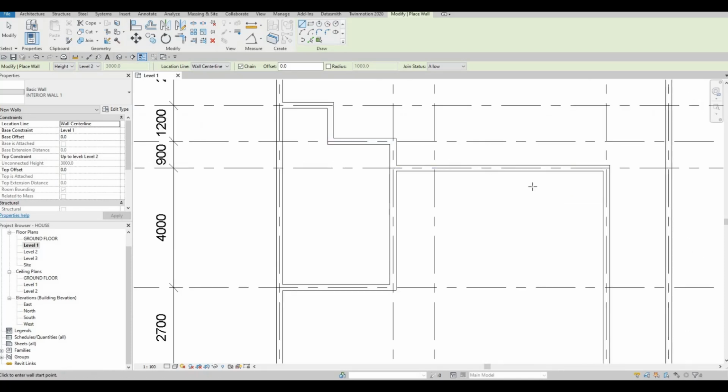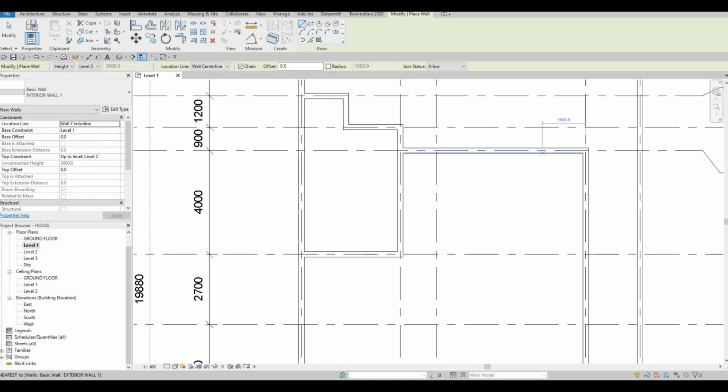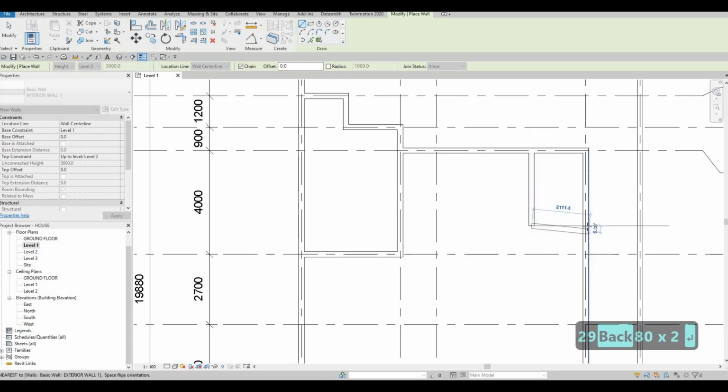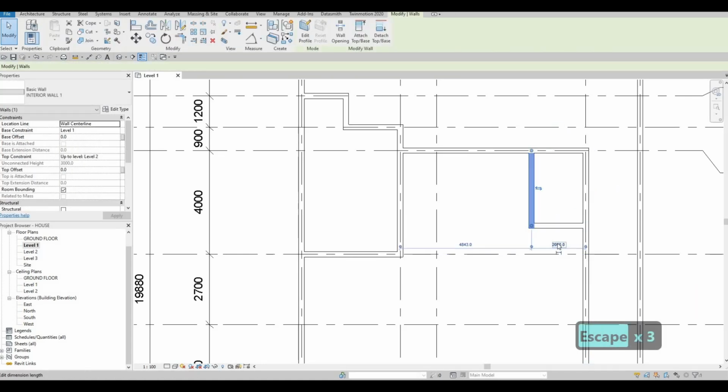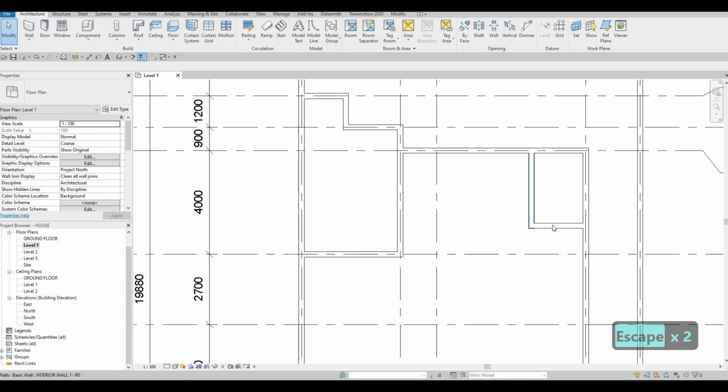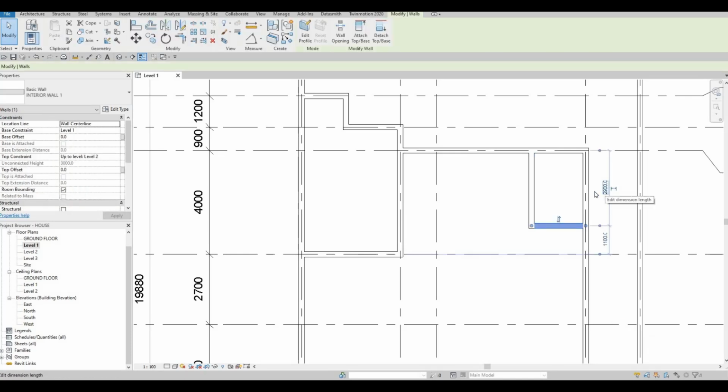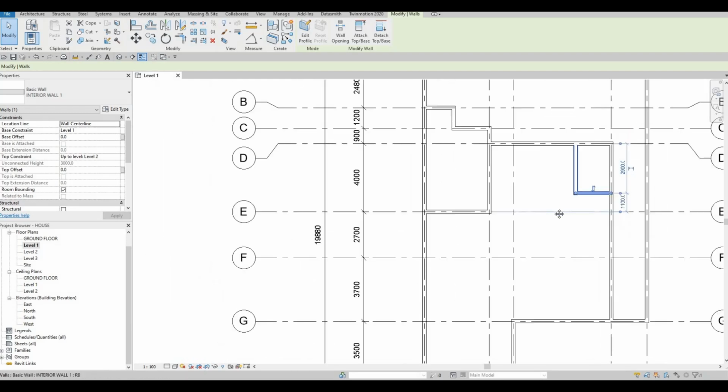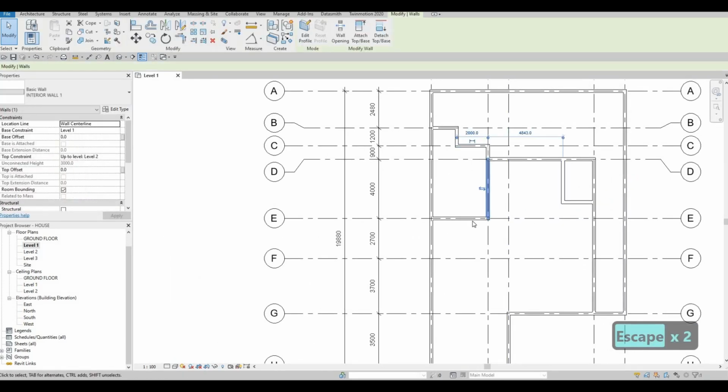And then here, we're going to add a laundry room right here, and it will be around 2000 from the wall right here. As you can see, you can always estimate this. You can put this one at 2900 or 2800 and then click right here. If you didn't do it properly, you can just select this wall, and then as you can see, you can change the dimension of this wall. You could put it at whatever number, but we have this at 2900.